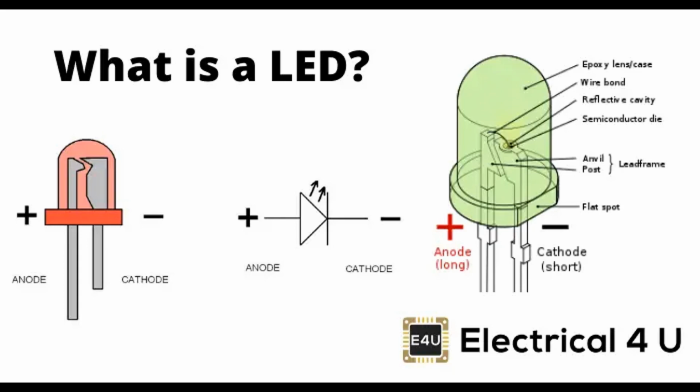Gallium nitride, GaN, is gaining popularity for its ability to handle high power levels and its efficiency in high frequency and power electronics applications. Indium phosphide, InP, is commonly used in high-frequency and optoelectronic devices, such as laser diodes and high-speed transistors. Gallium nitride on silicon carbide, GaN on SiC.